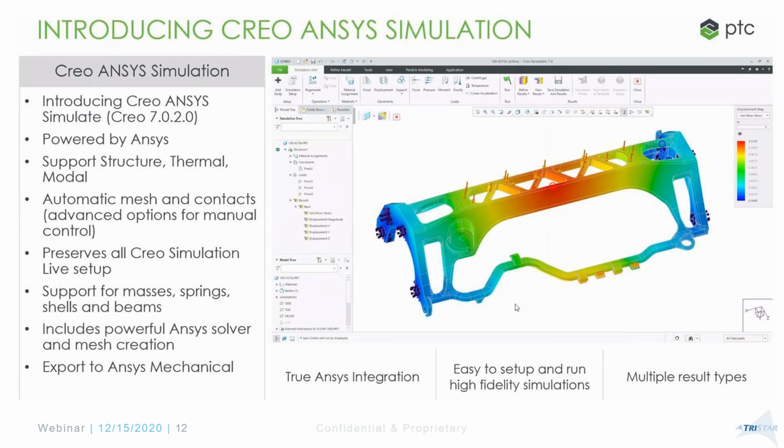Similarly, I might have components that I want to approximate as a beam element rather than a typical hexahedral mesh with solid idealization. Those are all supported inside of Creo ANSYS Simulation. So you can see why it's more of a high fidelity simulation tool compared to Creo Simulation Live, which doesn't support these. And as always, you have the ANSYS solver, the same solver that ANSYS Mechanical and ANSYS Discovery all use. So you do have that gold standard of ANSYS solutions built in.